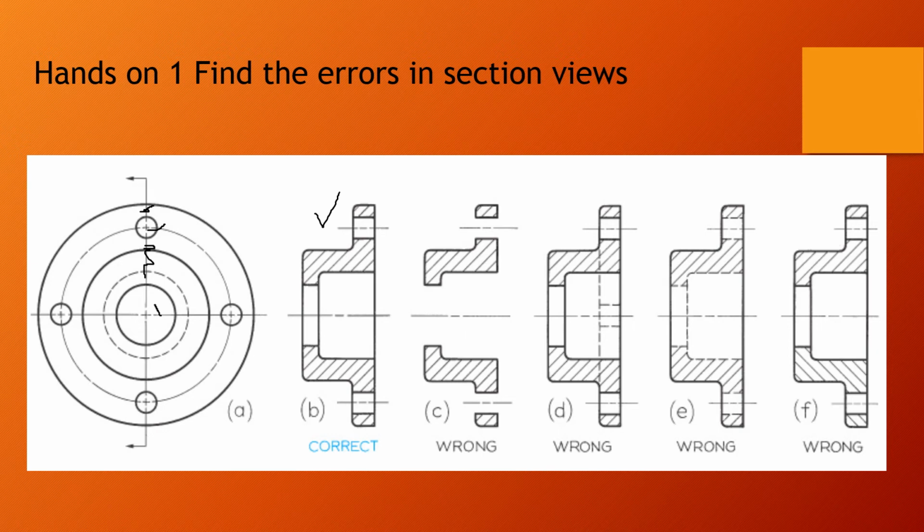So when we are making the sketch, we don't need to make hatching lines. So be careful, where there is a hole, we have to mention it, here is a hole. And where you cut the object, you can mention it with the hatching at 45 degree hatching lines. So please do not make the mistake.